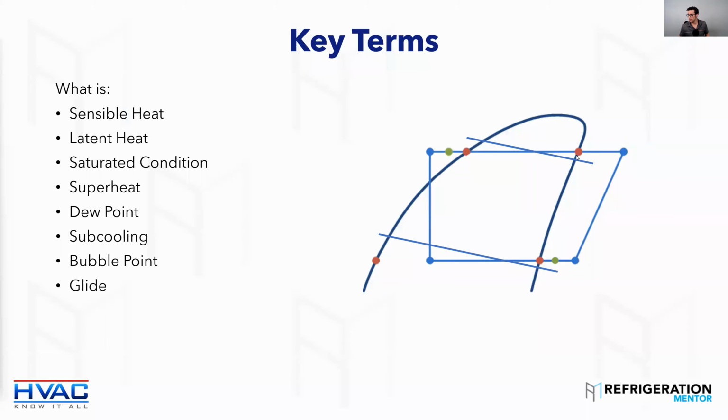Dew, right here. You want to do it right here because this is a different temperature, and if you use this point, you're going to have the wrong temperature. If you make that mistake, it could be too high a superheat or you could be flooding back to the compressor. Okay? And you always need to use the bubble point for subcooling.